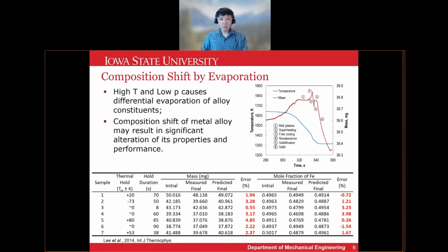in the vacuum. For most additive manufacturing processes, melt and solidification occur in an inert gas environment, which suppresses mass evaporation by orders of magnitude compared to the evaporation in vacuum condition. However, the maximum temperature could go up to 3000 Kelvin for the case of additive manufacturing, and this often causes mass evaporation, which is large enough to shift the composition.